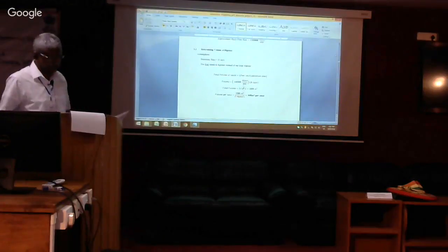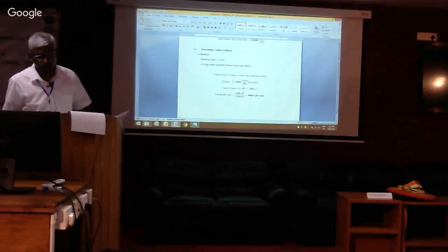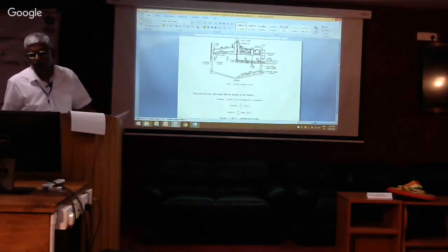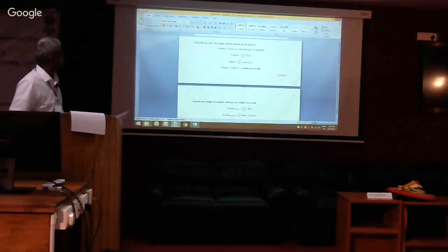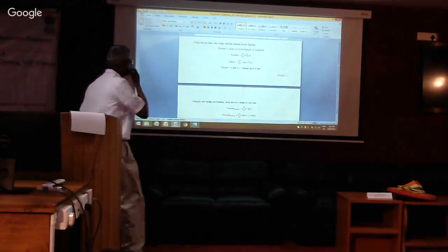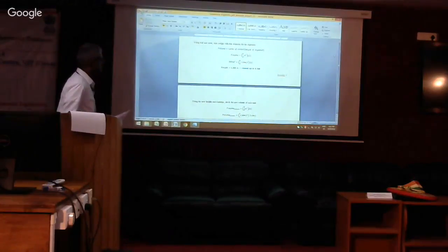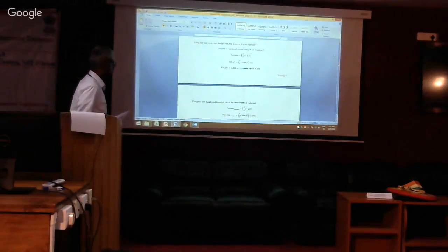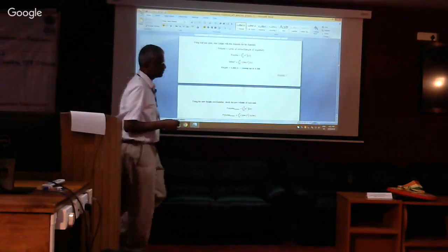Questions? Very straightforward. Now let's size the digester. If I take a 10-meter diameter, then the height would be about 6.5 meters. And so I will use 4 digesters, each with a diameter of 10 meters and a height of 6.5 meters. And if you want to cross-check, please do so.